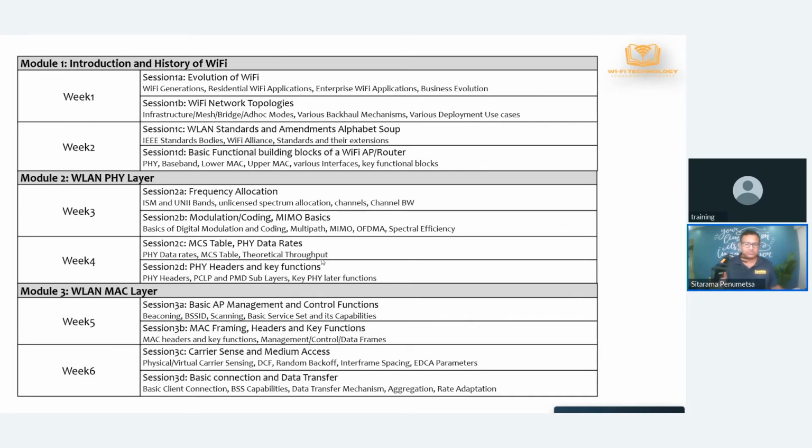There must be something that this Wi-Fi router does for your phone to be able to see that there is a network, right? Which means that this guy is going to broadcast some messages, and they're called beacons, right? Just like from a lighthouse, there are beacons, messages sent from a lighthouse for the ships to be able to see, to go to a specific place. Similarly, there is something called beacons that these Wi-Fi routers will broadcast. And then when the radio on this device receives those beacons, it will be able to see that network.